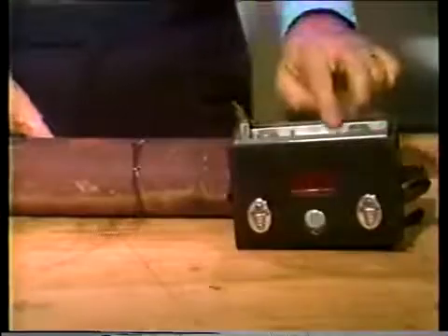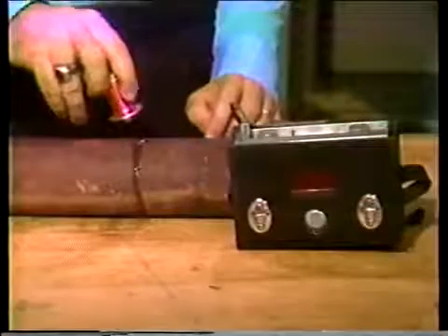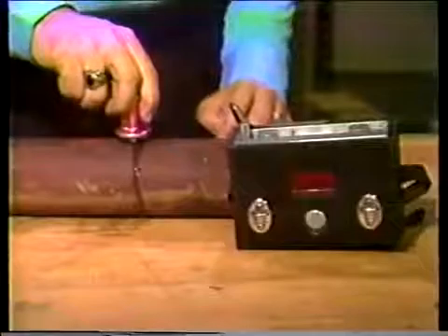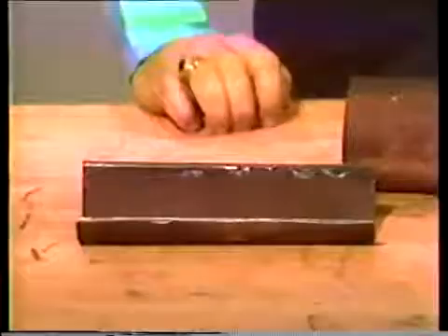Tube erosion may be hard to find by a visual inspection if the tube is worn down evenly. You're more likely to find erosion by using an ultrasonic thickness measurement device. Erosion may also be found inside the headers. Eroded headers may have gouges on their inner surfaces. This gouging may occur on the header surface opposite the places where tubes are attached to the headers.